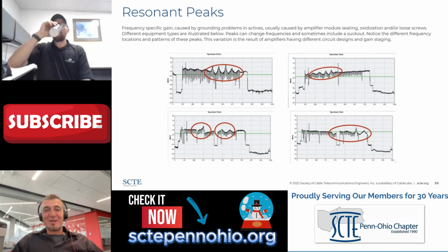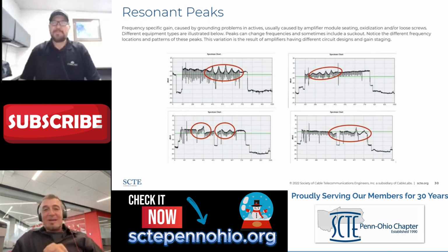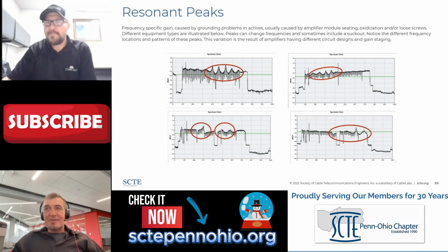All right, let's move on to resonant peaks, and we're doing a time check here. Okay. Resonant peaks are interesting, and we have seen these over the years. And if you've been around driving a bucket, it's not a new phenomenon to you. But the thing that's unique about resonant peaks is that there's a gain component to them. That means there's additive signal. And to have a gain component, by definition, it has to be on an active piece of equipment. And in this case, we know that it is caused by amplifier circuits.